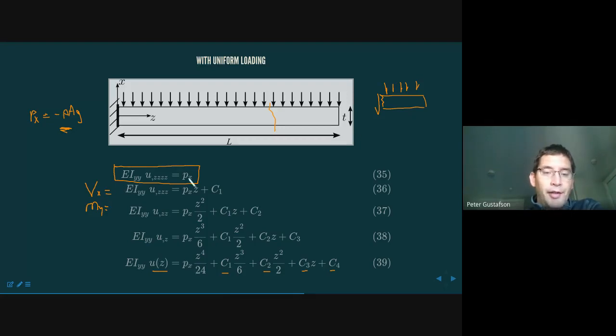We found that there is a distributed load equation, there's a shear resultant equation, there's a moment equation. By the way, this third equation down now is the EI value times, we'll say theta, where theta is slope. So this is a slope equation multiplied by EI, and then last, of course, is the deflection of the midline of the beam. So if you're solving these problems, recognize that each of these equations is meaningful. They're not just steps along the process.